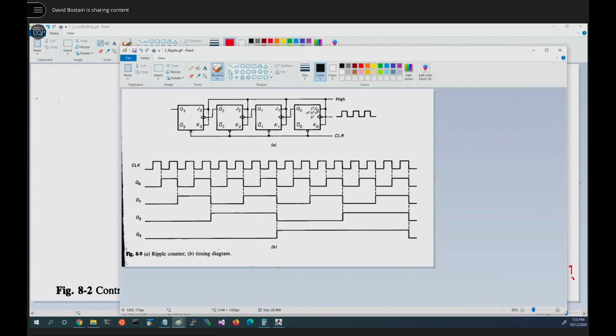So every time we get a falling edge, and internally this is probably really JK, MS flip-flops, and they're reflecting here the fact that it's happening on the falling edge. But it's really the second stage of the thing that's doing it. So the clock always is nebulous on these. Just make the assumption that it's falling edge and it's an MS flip-flop, unless I tell you otherwise.